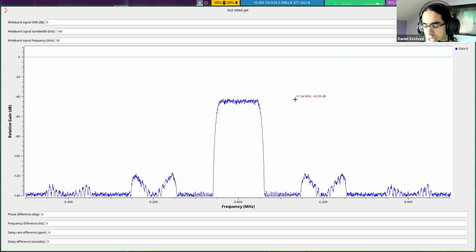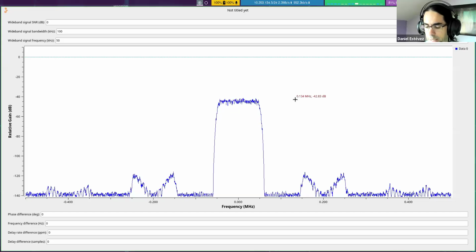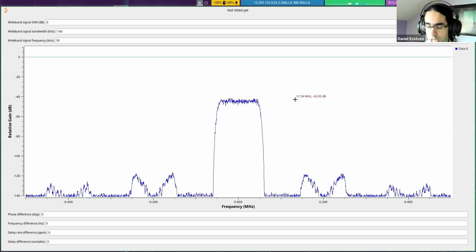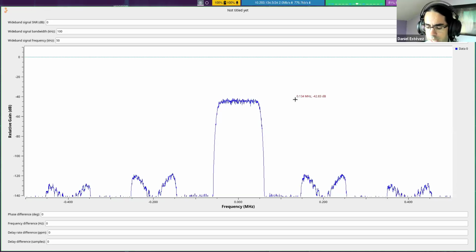And then it will transition into the western part of the sky. It will be closer to the western antenna. And so the delay will be basically saying that the signal arrives first to the west antenna. So this delay is continuously changing over time. And the consequence is that the Doppler seen by the two antennas is different. Basically, one of the antennas will see a slightly higher frequency than the other one.